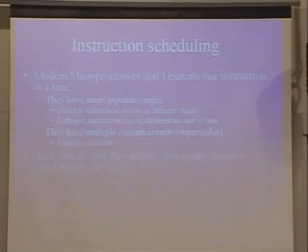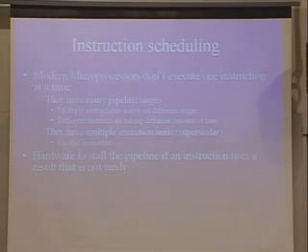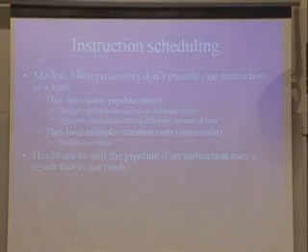If you have two instructions where one produces a value that the other uses, and the value is not available when it's needed, the hardware basically stalls the instruction in modern superscalars. In some machines you can't even rely on that: you have to explicitly insert no-op instructions because the data wouldn't be there. So there will be all these stalls.